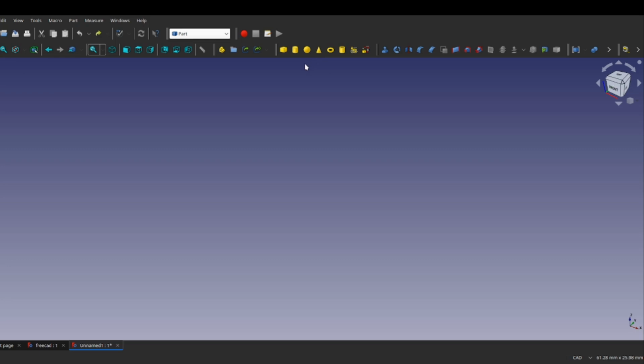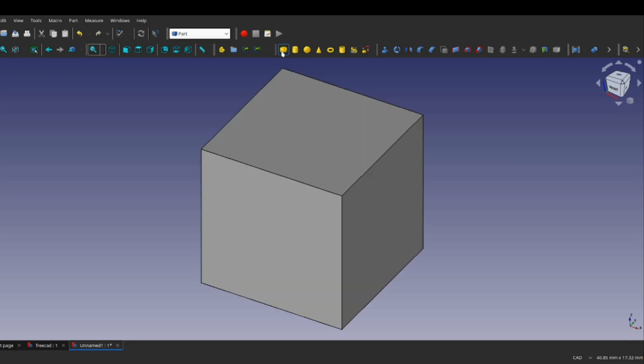The first thing I'm going to need is to make this little box shape. Before I move any further, I want to give you all a warning. The primitives, from what I believe, are basically empty inside. If I go to Sketcher or Part Design, I'm making a part that's, quote, solid through and through.